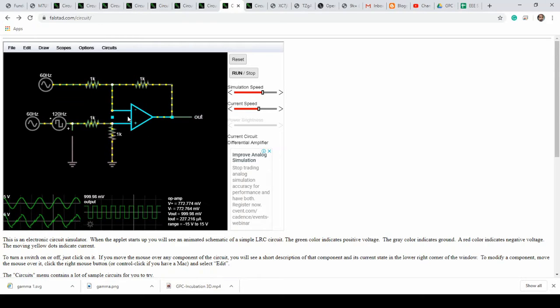So what happens when the voltages are exactly zero? It crosses the zero. When the voltages are different, and if this is greater, it switches on and goes high. When it's lower, it goes low, and it crosses zero every time it switches over. So you get a square wave that crosses zero, and this is possible with the differential configuration of the amplifier.